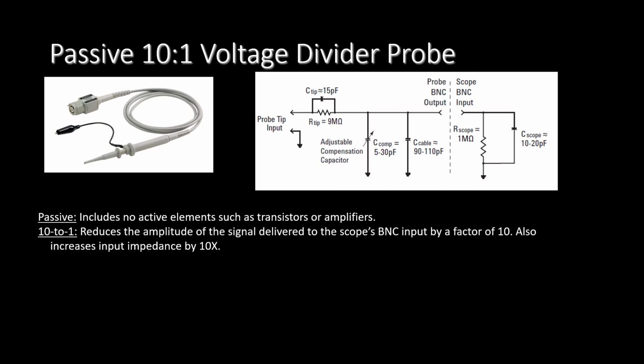With this type of probe, you cannot measure the voltage across two mid-circuit components. This type of differential measurement would require a special differential active probe. Note that you should never attempt to complete a circuit using an oscilloscope probe.